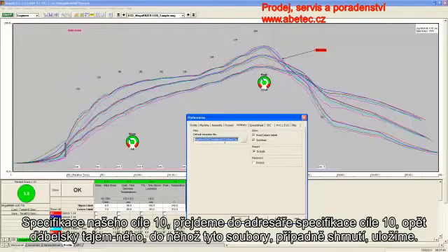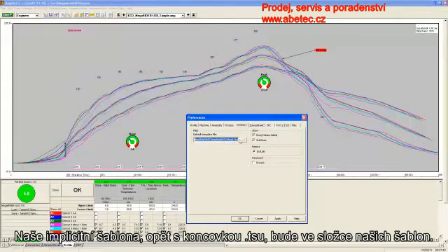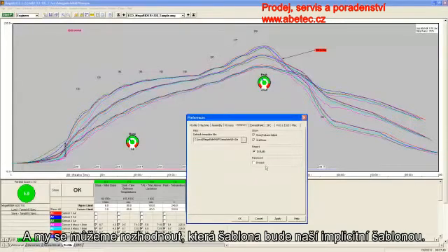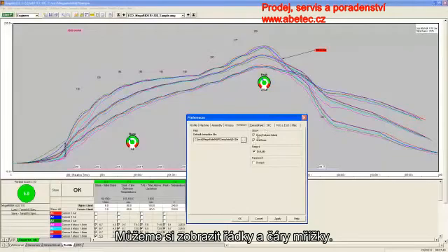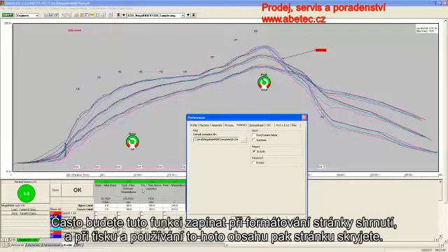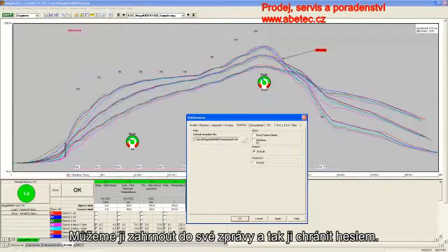Our summary that we looked at. Our default template, again with the TSU extension, will be in our template file folder. And we can choose what our default template should be. We can choose to show our rows and grid lines. Keep note that if these rows and grid lines are visible in your summary, they will print out. So quite often you will turn these on when you're creating a summary page for formatting use, and then you will hide their visibility for actual printing and utilization of that summary. We can choose to include that in our report, and we can also password protect it.